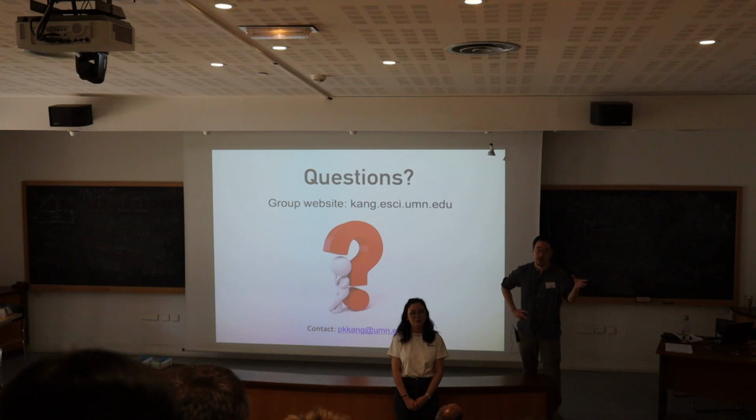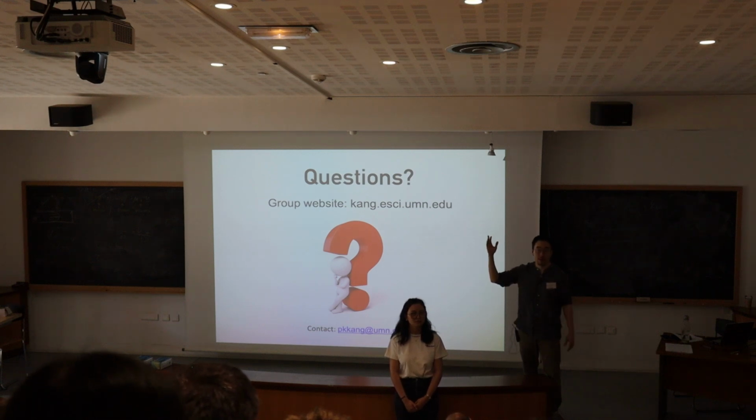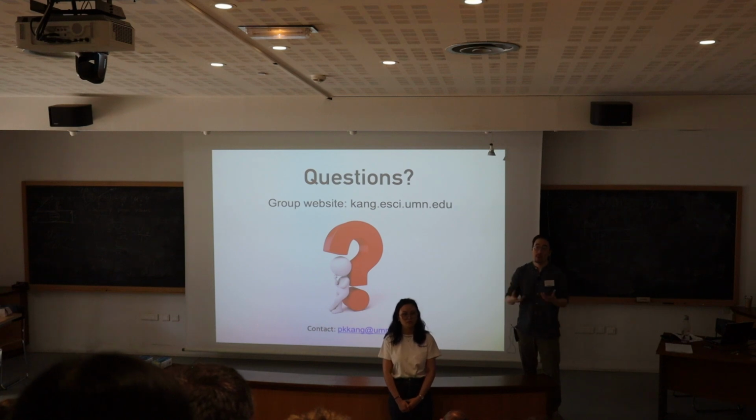Because what's happening at the injection borehole will really impact the overall operation. There's no question that near the injection borehole the Reynolds number will be even 10 to the 5, and then it will decay as we go out. But if you want to understand clogging, I think this can play a role even in porous media. So what would be the typical Péclet range where you think these effects matter? Because Reynolds and Péclet go together.